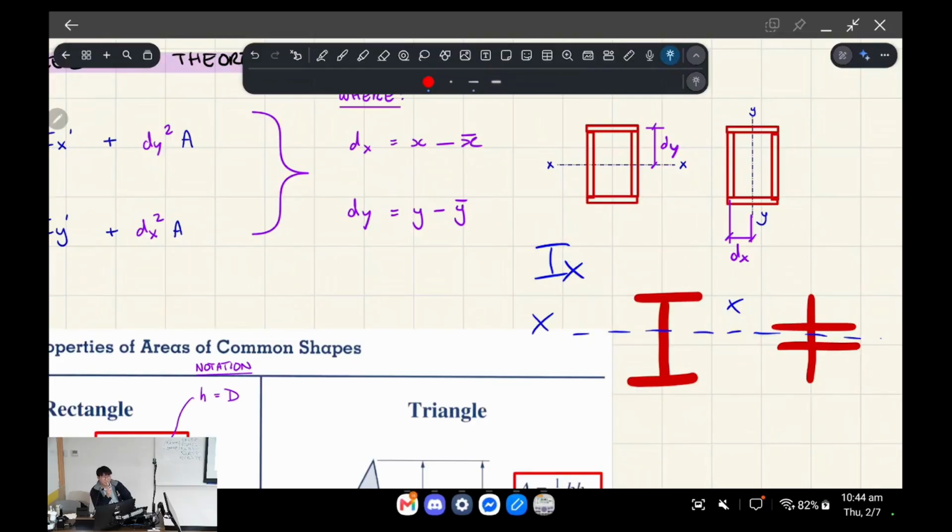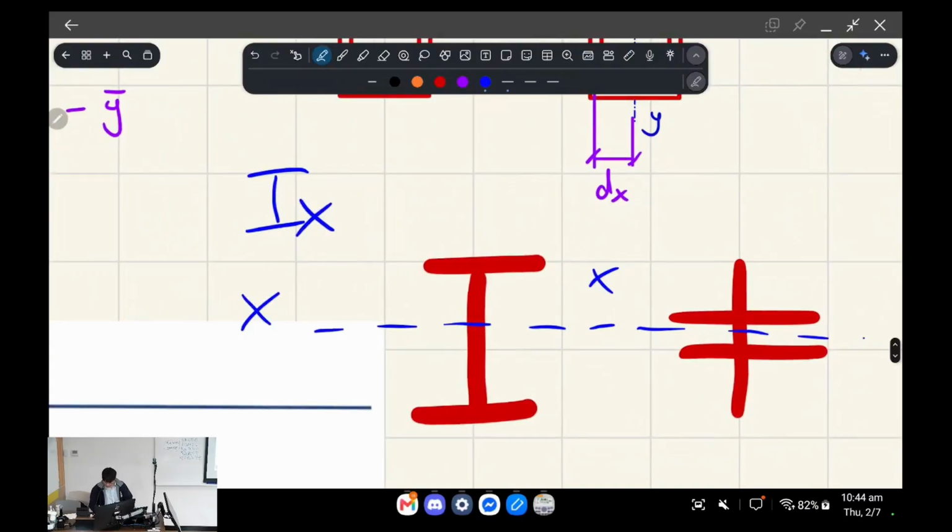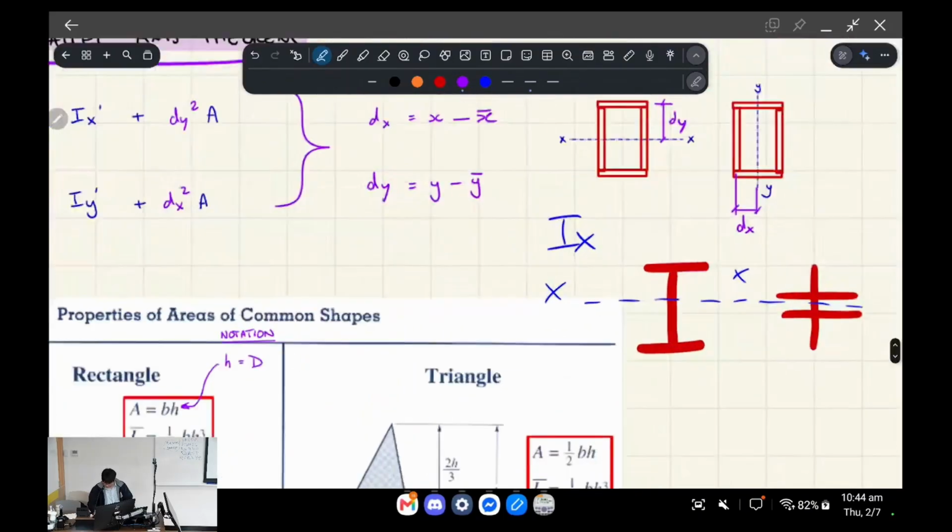This isn't terribly intuitive, but I just want you to think about it. Which one is going to bend less? Yeah, when crossing the river. It's actually the shape on the left that is going to be stiffer. So it's not exactly intuitive as to why right now, but the answer lies in parallel axis theorem.